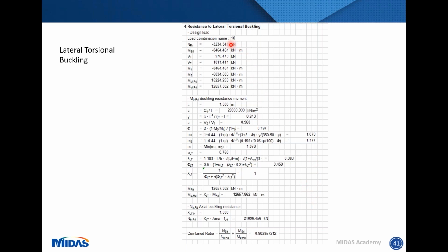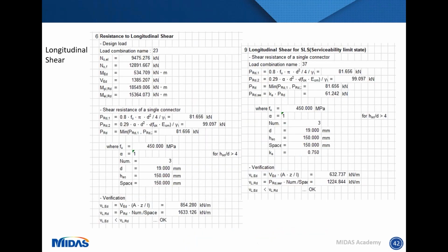And these are the design loads that have been entered in for that particular element, and the load combination that goes with this. So if you want to, you can go back and do a quick check to verify these values, and also to verify how the software is producing the buckling resistance. But this is at least a nice quick tool when you're looking at your beam design to be able to use and just see how the software, or at least how your section, is doing. And if you're happy enough, it's an easy output that you can also include in your design calculations.